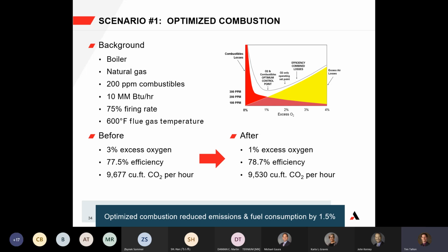By monitoring with a methane detector by itself, you can also monitor for fuel leaks and flameouts during operation that could contribute to unsafe conditions. Fuel leaks also directly relate to emissions as well. So it just provides an additional safety point for monitoring. Does that answer your question, John, or should I be more specific? No, that's fine, Tim. It's an additional safety point, but it also provides that kind of back-end monitoring.